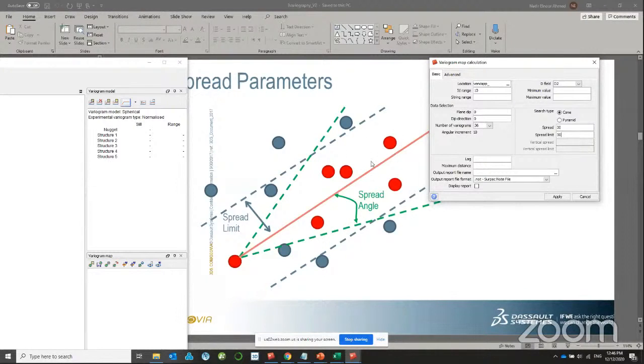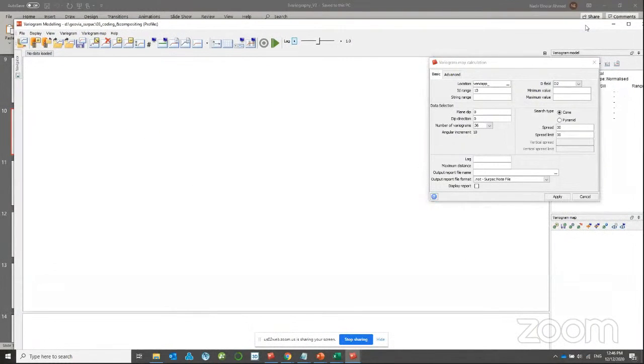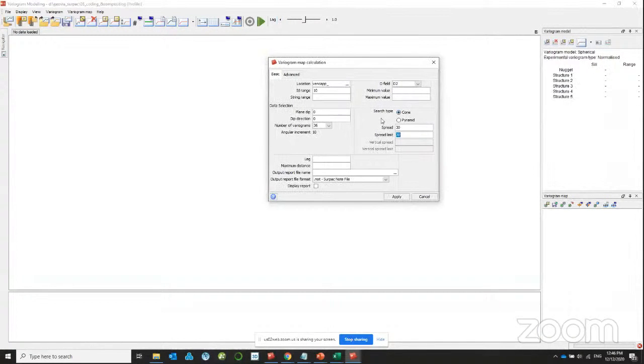The variogram is just subtracting the values from each other, separated by a certain lag, and then squaring the difference and then summing that difference divided by 2, like a semi-variogram. The software will generate it automatically for you, so you don't need to do this calculation. You just start with 20 meters. Maximum distance, let's make it about 400.